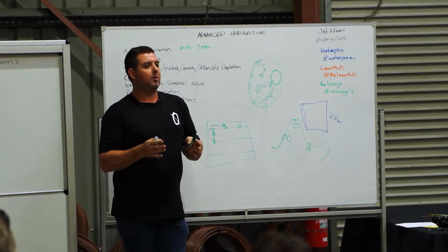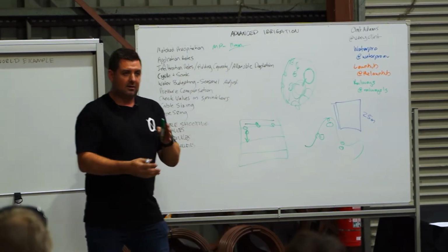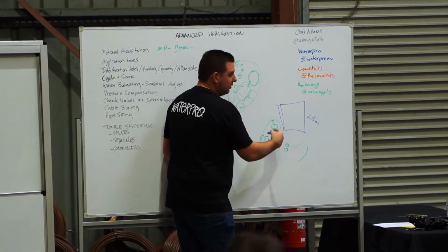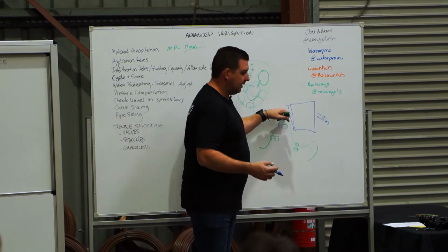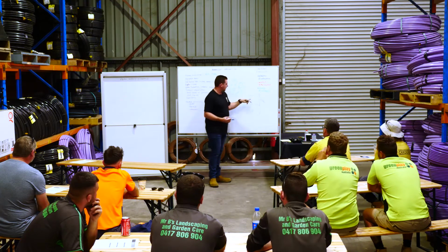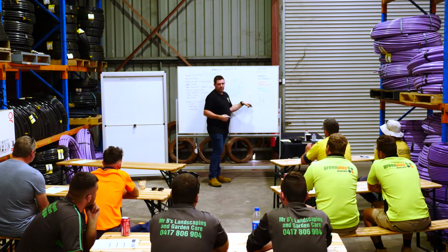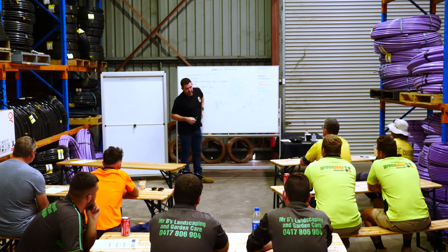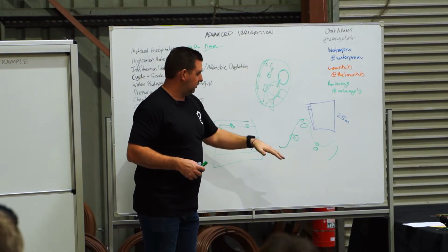It's hard when it's a job that you're not going back to, but if you're doing maintenance on a job, you can start to get a real-time feeling for what's going on, and you don't want to let this go too low. Usually a soil profile will come out of winter relatively wet, and then as the weather gets warmer and the plant becomes less dormant, it starts using the water. So it might use 2 or 3 mil of water every day. We don't want to be putting 2 or 3 mil of water in an irrigation event every day. It's not enough water for it to get into the soil structure.